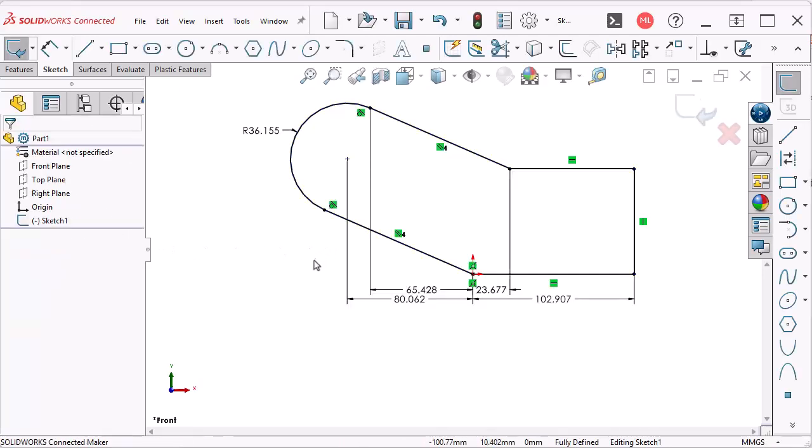It doesn't mean that what you get as a result will be editable later on. That's one thing that's important to remember. I don't think it's so important to have a fully defined sketch that you'll just take whatever the computer gives you. I think a fully defined sketch has to be well thought out. Otherwise, you might as well not fully define it.